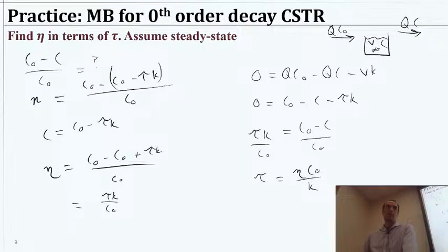And the answer to that would be yes, because for a first order reaction, it doesn't matter how much is there, you're removing a portion of it over time. So it doesn't matter how much you start with in that sense. For a zero order reaction, basically anything that's not first order, our efficiency should be tied to how much we started with, right? So in this case, maybe I'm happy enough with that, because we got there this way too. Okay with that?